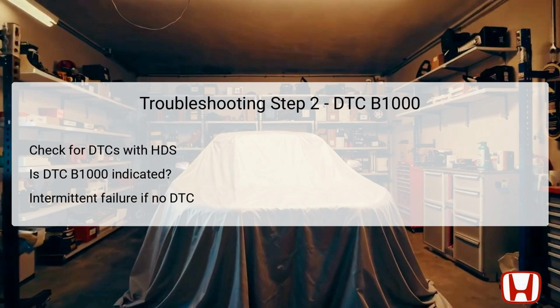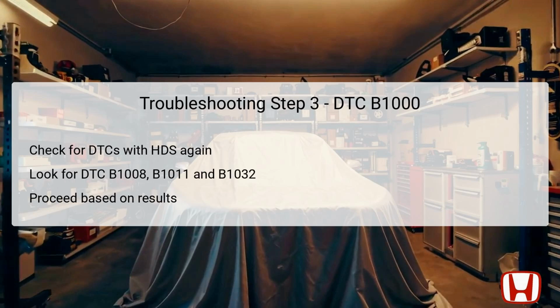Additionally, the technician should verify the battery condition and assess the charging system, as these can also affect electronic communications. Next, the technician will again check for DTCs using HDS, this time looking specifically for related DTCs such as B1008, B1011, and B1032. If any of these codes are present, it indicates a broader communication issue involving multiple control units. This scenario directs the technician to the next diagnostic steps to identify the problematic control units.